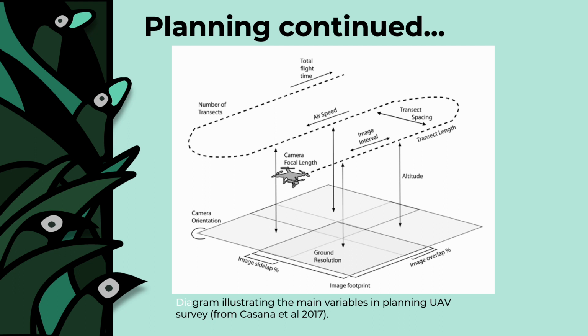Pre-flight planning also includes determination of airspace status over the survey area and gaining approval if the planned flight occurs in controlled airspace. Consideration of weather, wind and lighting conditions, and condition of the UAV hardware and firmware is also vital.